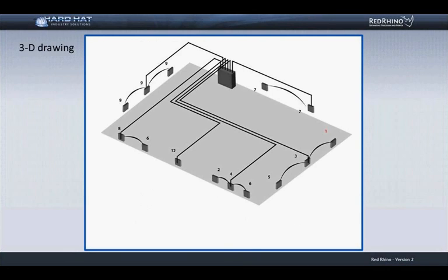To better understand what the two-dimensional drawing represents, I'll also use a three-dimensional drawing of the same building. This is not a view you'd normally have available on your project blueprints, but we will use it because it shows how the conduit runs out the top of the panels to the junction boxes. From the junction boxes, the circuits extend via MC cable to the devices.